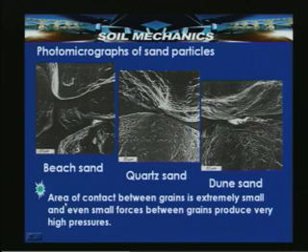The important point to be noted is that the area of contact between grains is extremely small, and even small forces between grains produce very high contact pressures. Because of this, even a small force can induce very high contact stresses between the grain particles.